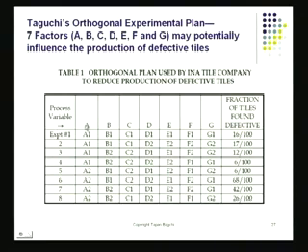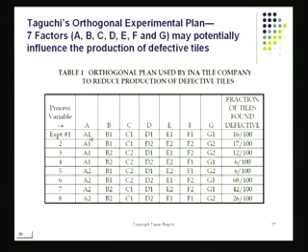The process factors are these A, B, C, D, E, F, and G. And he set up this matrix that comprised 8 trials. And for each of these process factors, he chose 2 levels. These were the extremes of the working range in which these different variables could be changed, could be altered. So the first one could be changed between A1 and A2. Second one could be changed between B1 and B2 and so on. These were distinct numbers. These were distinct settings. But they were clearly 2 settings for each factor.